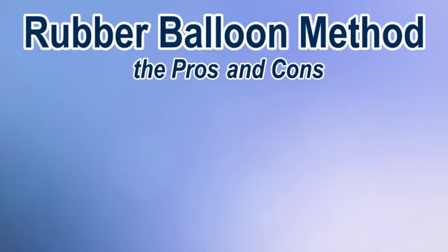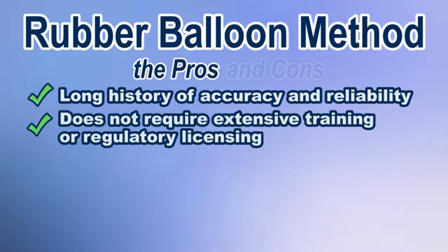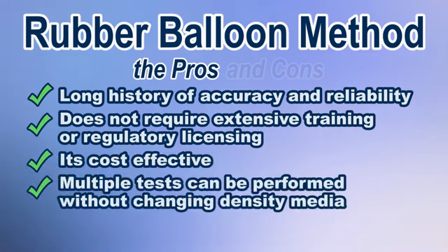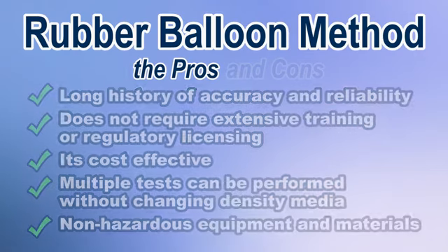Pros of the rubber balloon test are: it has a long history of accuracy and reliability. It does not require extensive training to perform or regulatory licensing for use. It's cost-effective. Multiple tests can be performed without changing density media. And equipment and materials are not hazardous.